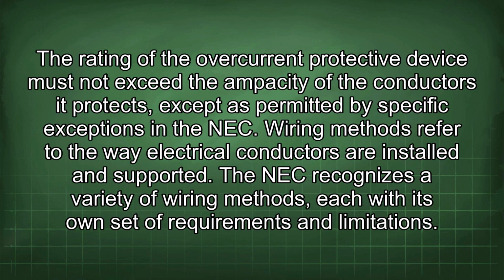The rating of the overcurrent protective device must not exceed the ampacity of the conductors it protects, except as permitted by specific exceptions in the NEC. Wiring methods refer to the way electrical conductors are installed and supported. The NEC recognizes a variety of wiring methods, each with its own set of requirements and limitations.